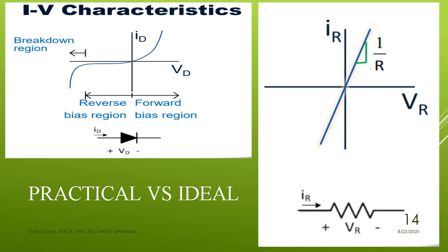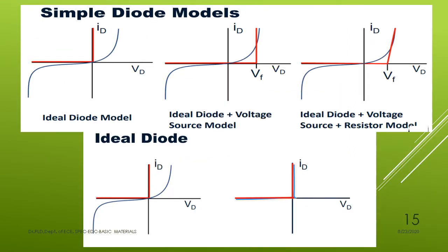Dynamic resistance uses the difference between 2 points, delta VF by delta IF, and leads to the dynamic resistance of the PN junction diode in forward bias. The same phenomenon applies for reverse bias also, both dynamic and static resistances. In the same way, we can calculate 4 types of resistances: in forward bias, dynamic and static, and in reverse bias, dynamic and static.